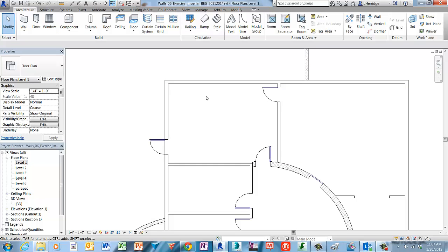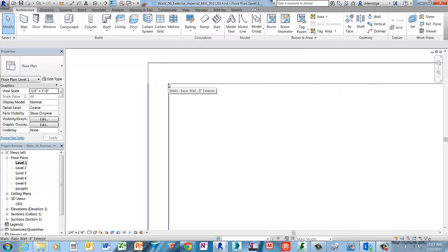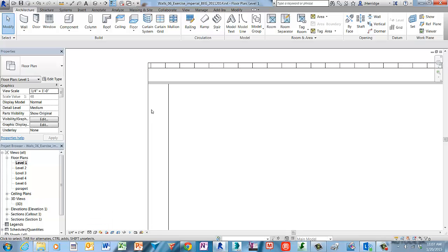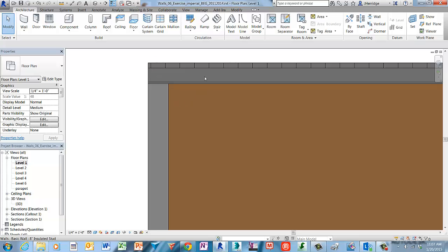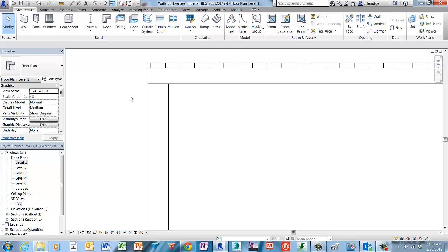And then the last step is to actually make a wall substitution in place. But before we do that, let's just confirm that the wall that you currently see on screen is actually the new wall type. It's hard to discern that until we change the detail level to medium, and then you can see the internal wall layers display on screen. I just turned on shade mode to make that a little more legible for you. I'll turn shade mode back off, or just type in HL for hidden line view.